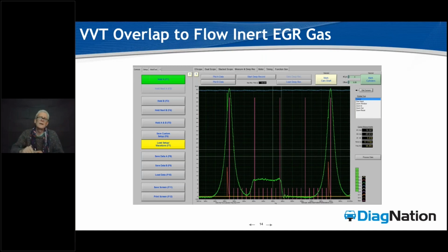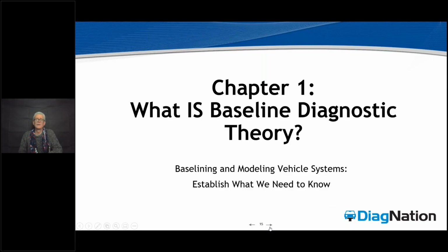misdiagnosis. So, guys, scan data, we're going to cover that as we come into the end of the class here. And scope. The mechanical fixes we're catching today, I'm going to repeat it, are 70+% of gas direct injection drivability. And we're not catching it with a scanner, okay? We can, it just requires a lot of specs and study and, to me, wasted time and misdiagnostics, okay?